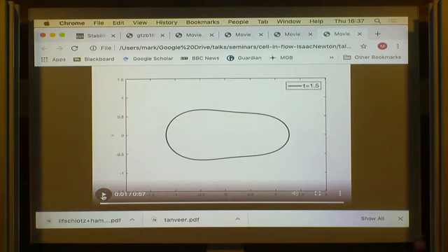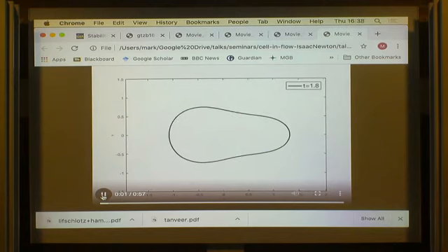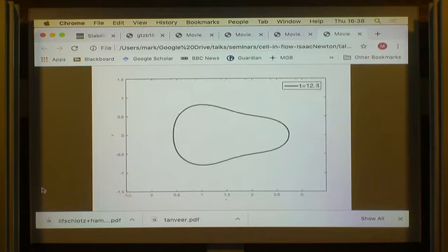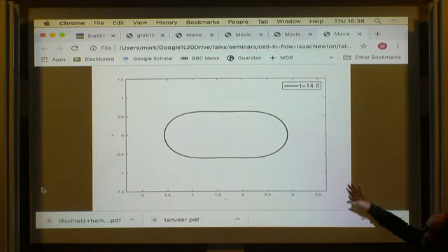Again, there's one unstable eigenvalue from the linear stability calculation, and the unstable eigenfunction looks like a mode 3 shape, which helps to interpret what you see in the movie. Again, it looks static for a while, then it bulges outwards in a mode 3 type shape, which at the same time is moving downstream slightly, and then this motion continues.